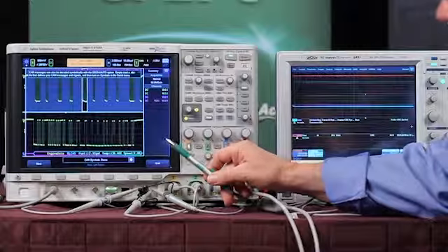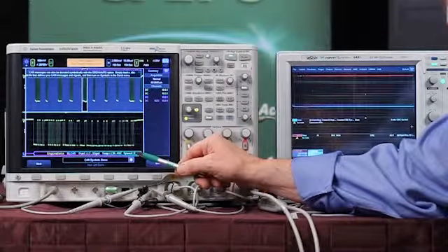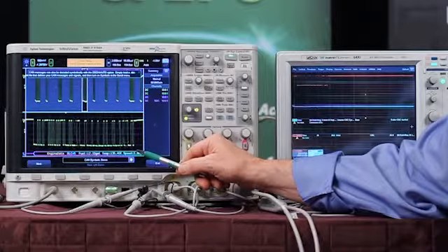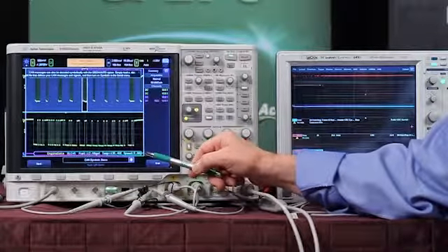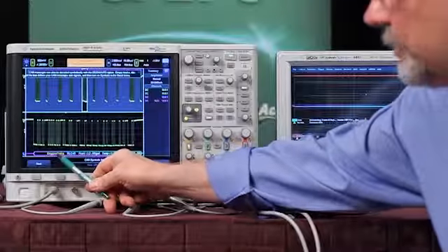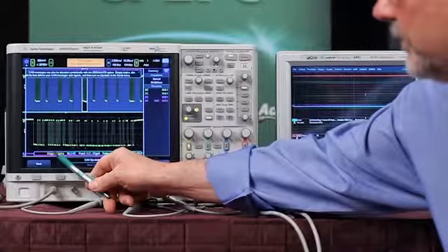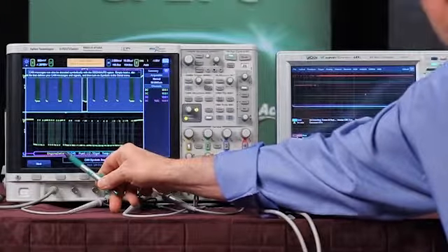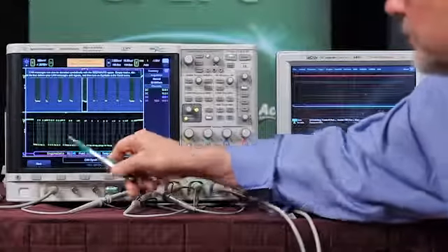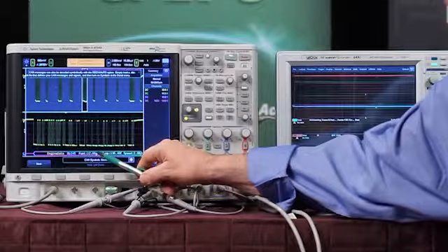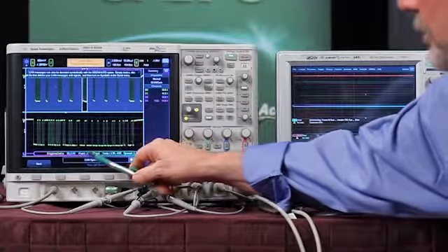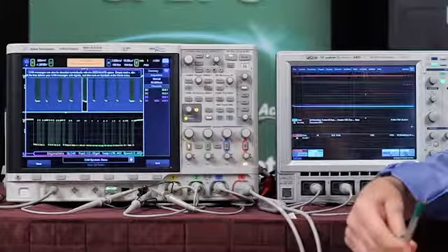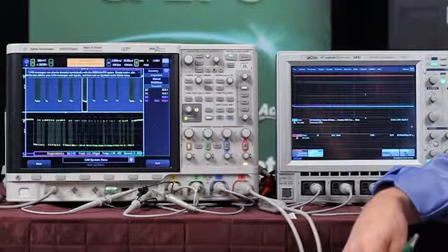We're now showing an example on the Agilent oscilloscope of CAN symbolic level decoding. Now, no longer is the bus being decoded in simple hex characters, but now we're displaying in more human terms. In this case, the frame ID has been translated into engine data, which is called a message. And here we also have what is known as signals. Here we're showing fuel, temperature, speed, all of this being converted from hex into symbolic code.